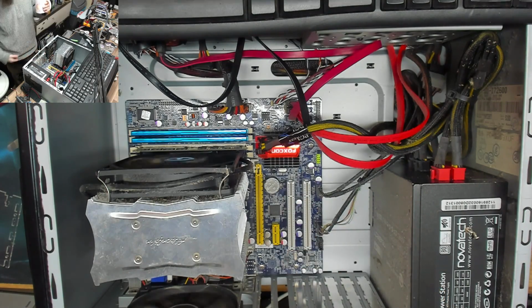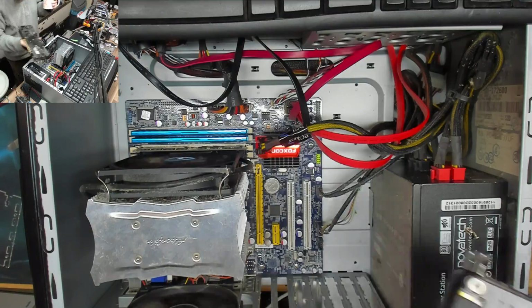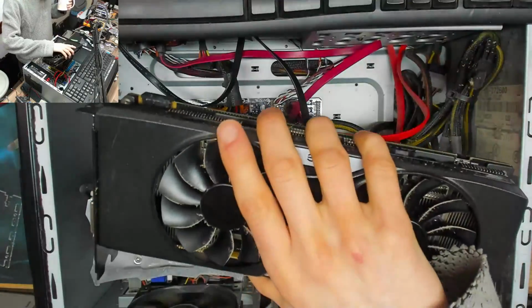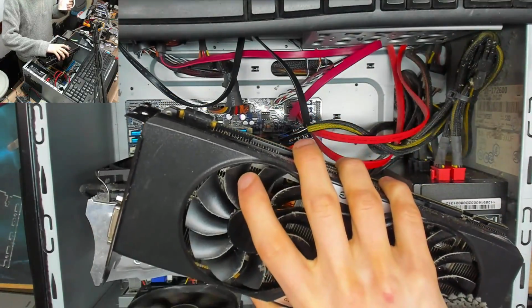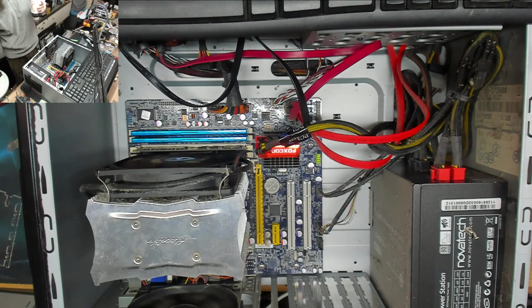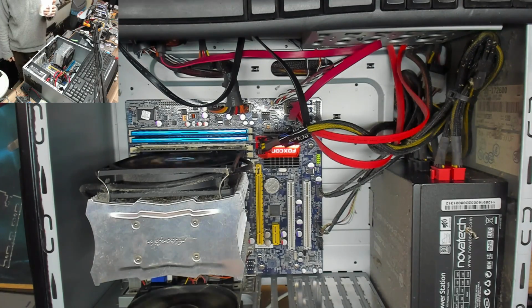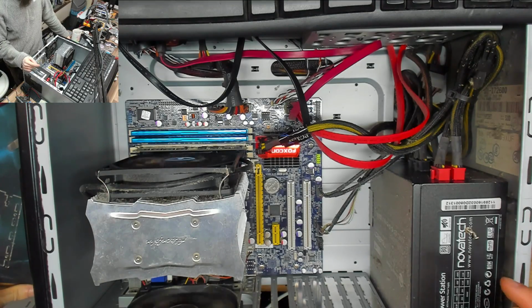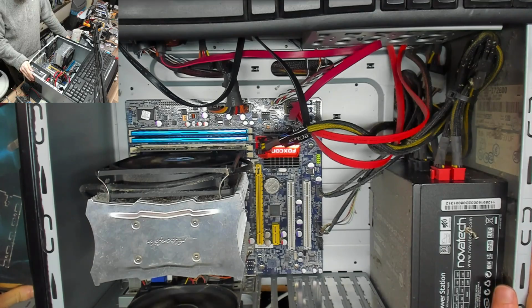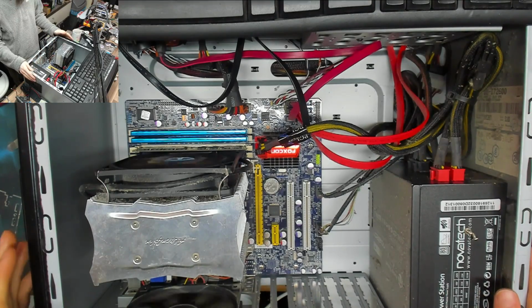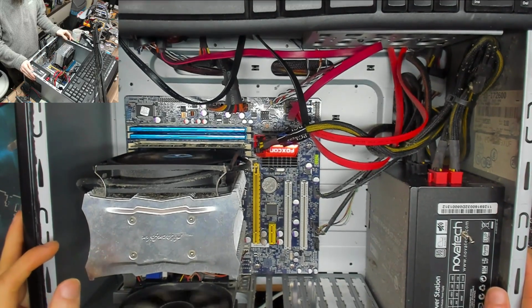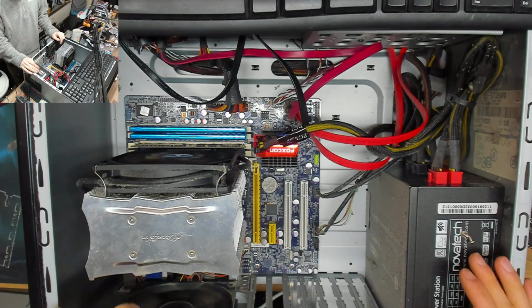And then after that, I think the next step will be to do some testing with this graphics card. Maybe plug that into another machine and just see if we can reproduce the faults there. It looks like we might have a Duff graphics card, is my early guess at this point. Of course, we also need to consider that if there's a problem with the power supply, it may work without the graphics card because there's less of a load on the power supply. So that's also a consideration.